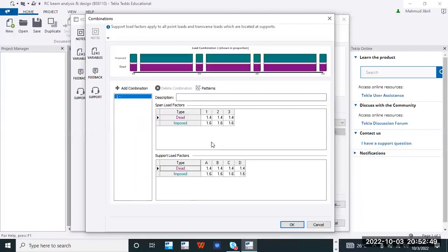But when it goes to a 4 span beam, the load combination will go higher, depending on the number of spans that you have. Those who are good in analysis will know such kind of things, and you must find the critical condition, the worst case condition of such a structure. Normally, when you have a beam which has too many spans, the center support is the worst case condition at that position. Then you need to find the worst case condition at that support. That is to superimpose the load on the adjacent spans near that support.